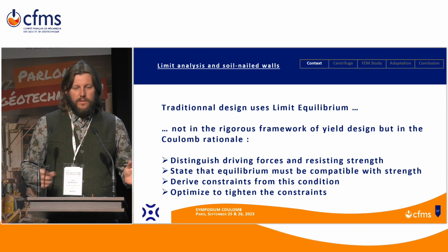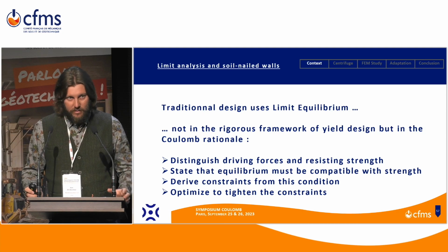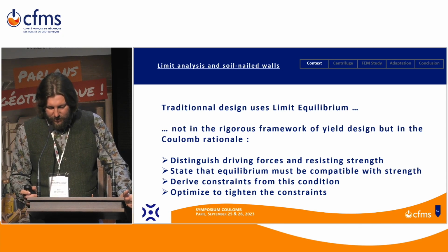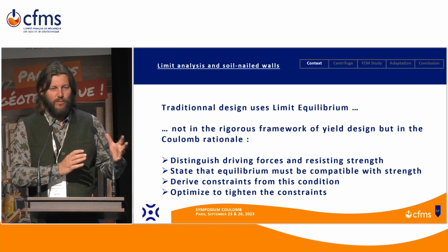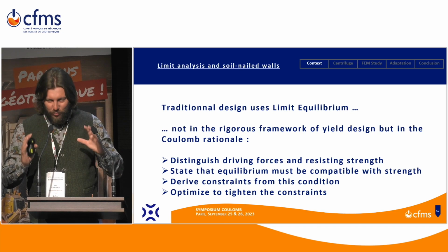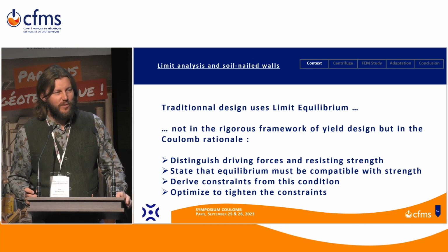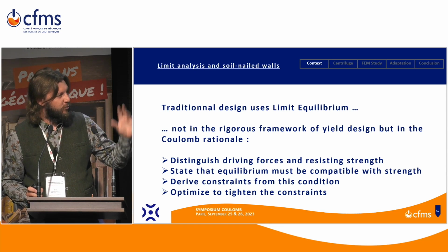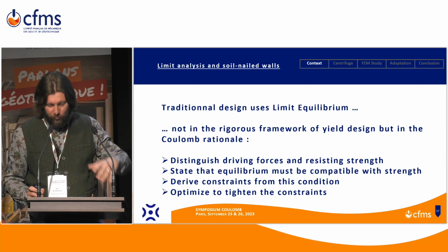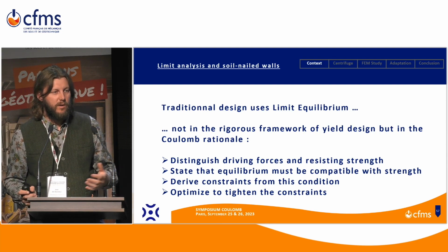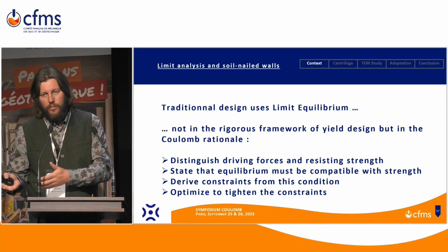Now I'm moving towards the way we design soil nail walls, and traditionally we are using the techniques of stability analysis. So it pertains to the Coulomb rationale as presented by Professor Salençon. It's not the rigorous framework of yield design, but the ideas are here. So we distinguish the driving forces and resisting strengths. The driving force is the weight, and as stated before, the resisting strength comes from the soil and from the nails.